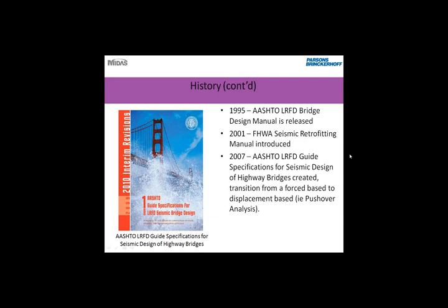So an example of a type of analysis that's done to look at the displacements is a pushover analysis, which is becoming more and more common. Now, this isn't to be confused with the topic that I'll be talking about today, displacement time history. My presentation is still a force-based approach. Displacement time history is still force-based. This is just simply looking at the displacements of the soil on the substructure in a seismic event.